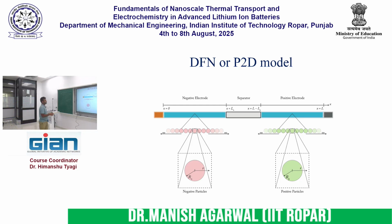And the particle has become uniform. Rn is the size of the negative electrode particle and Rp is the size of the positive electrode particle. Right? So the problem has simplified a lot. And why has the problem simplified? Because earlier for the battery I was solving either a 2D problem or a 3D problem. Now I will be solving only a 1D problem, which is computationally much cheaper compared to the 2D or 3D counterpart. And the particle also is now spherical.